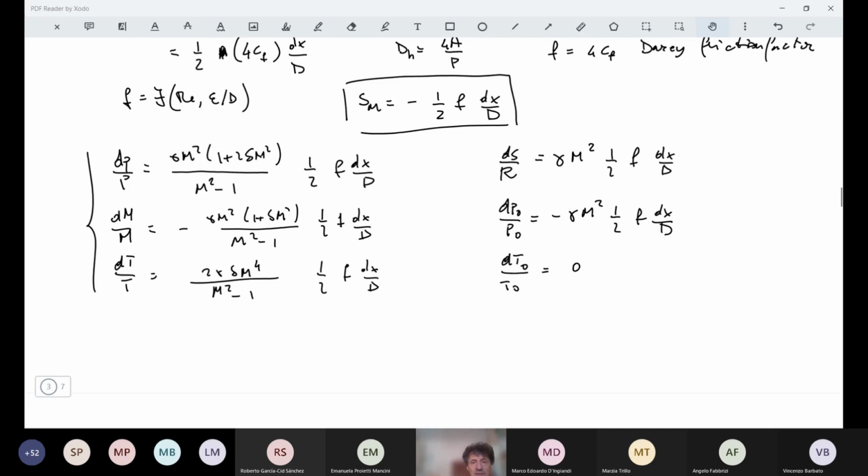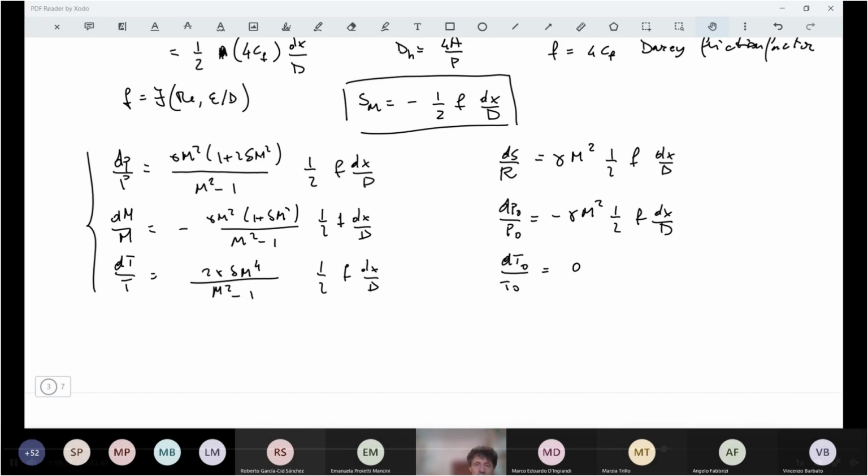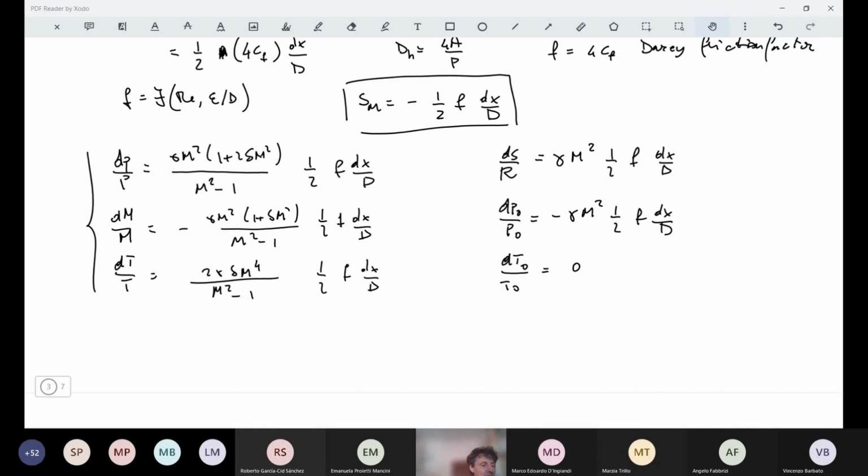So you see that here we do not have an isentropic flow. We do have changes of entropy. This is positive, the dx is positive by definition, as a consequence also the dS is positive, and it's clear that dP0 is negative. So we have a non-isentropic flow because there are currents related to the different momentum. We have our wall, where velocity is 0, and the core flow. So because of friction at the wall, we have these currents, and we have a flow which is not isentropic. The flow is adiabatic by assumption, and we have a decrease of total pressure as shown here.